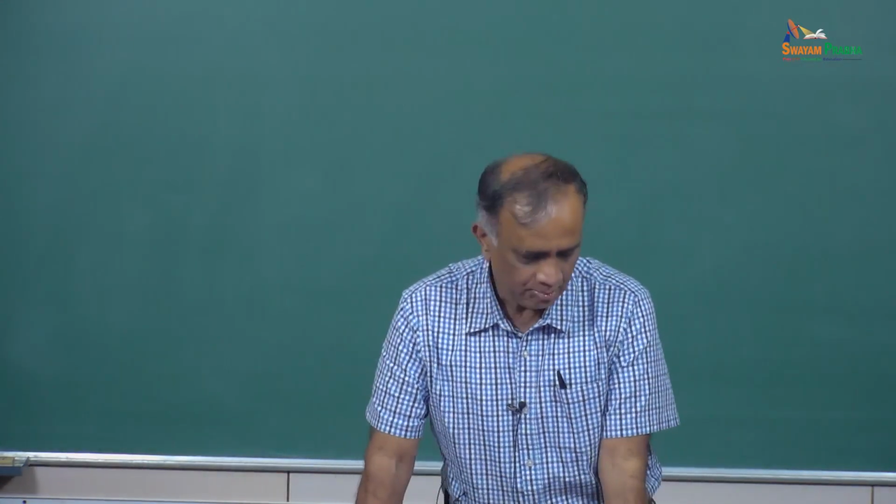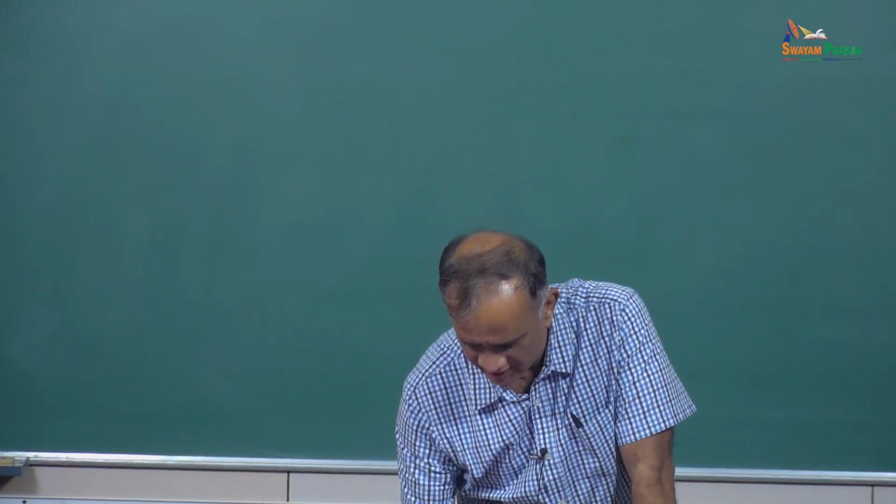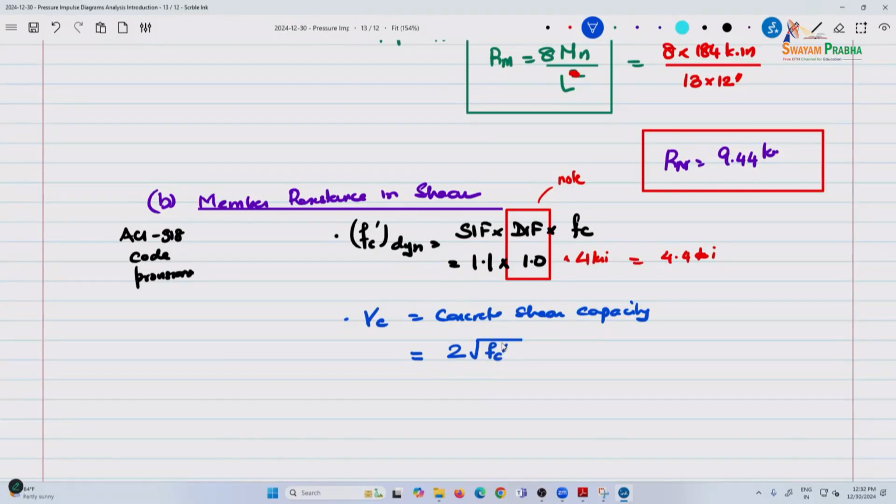But even the simplest form has changed, but we'll use it ignoring the effects of reinforcement ratio. The reinforcement provides additional shear strength, like shear stirrups or dowel action in slabs. So ignoring those actions, for our course purposes this is fine.